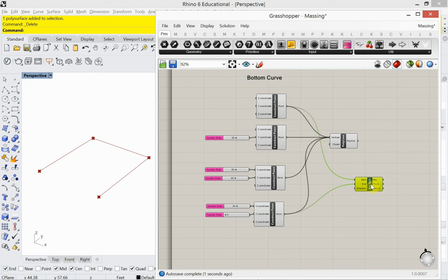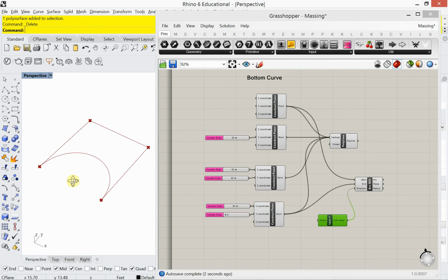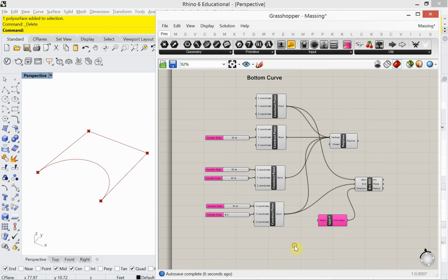Now the direction that I want this arc to be, so I want it to be out here. So this is going to be a negative y direction. Okay, I'll double click, type in y, choose unit y. See, that's the positive direction. But if I put in a negative value here, I can't just double click and type in negative 70 because it wants to do a subtraction.